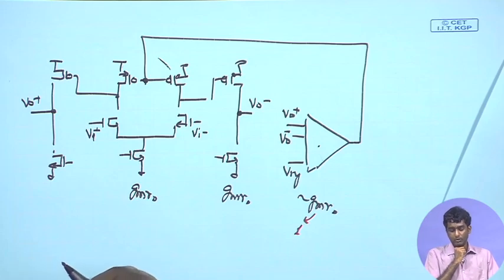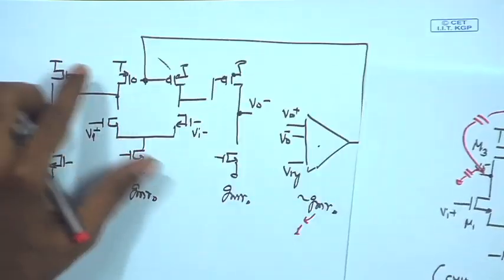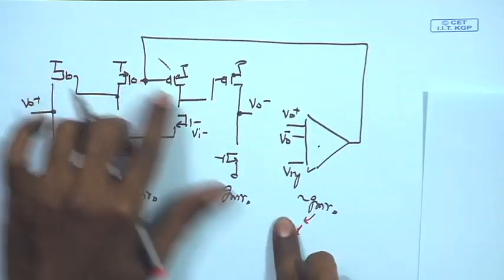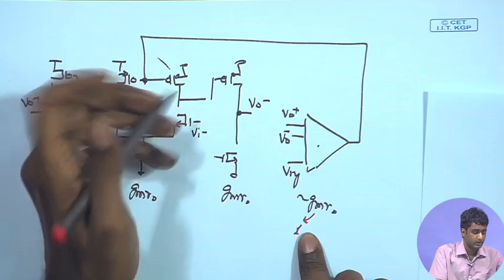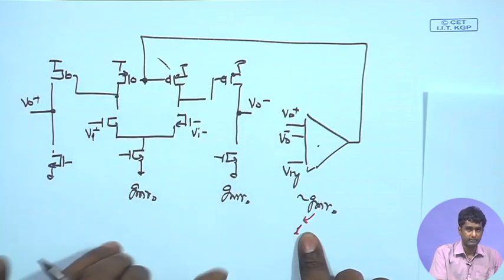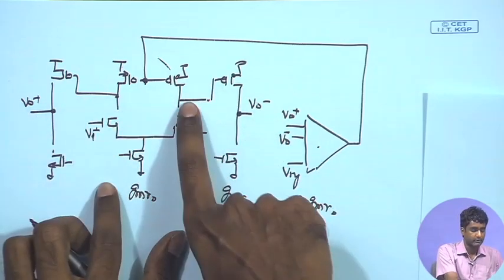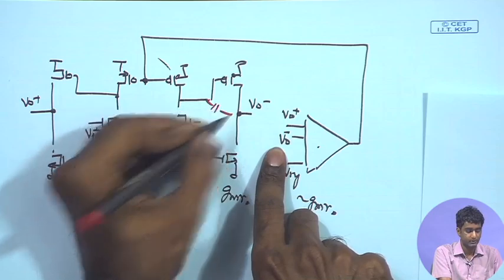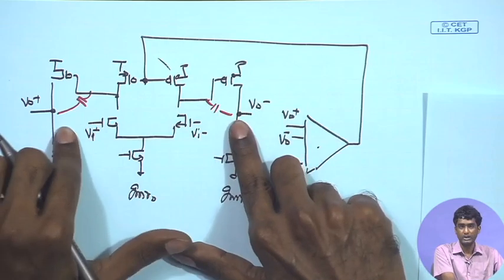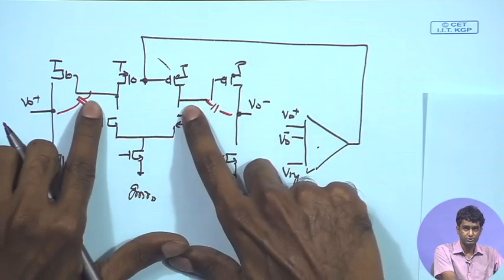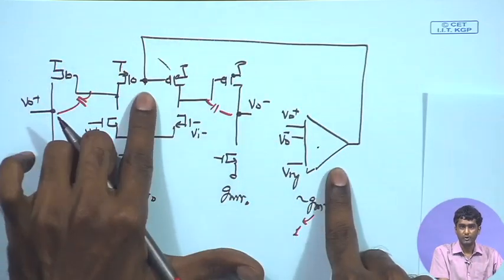However, in that case, since we have the overall two stages in the differential gain, it can be compensated using the differential stage itself. For example, if we just rely on the capacitor connected between the first stage and the second stage, if we put a CC over here and a CC over here, which is generally done for the differential mode compensation, in the common mode also these two CC are going to come as they are, and they will compensate the common mode response also.